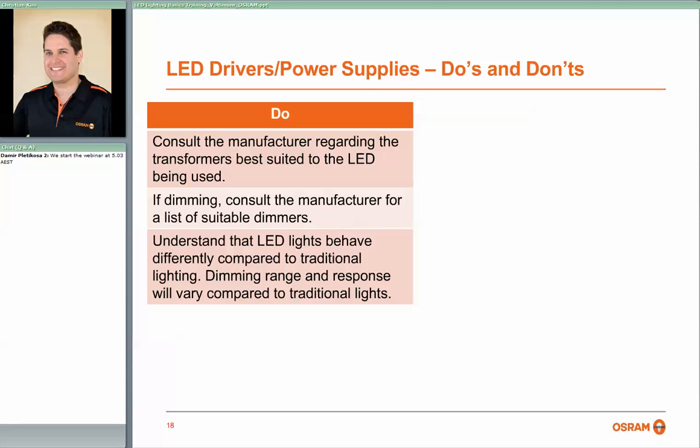products, which are designed to work on existing technologies such as halogen transformers and so forth, where you're just replacing a halogen lamp and putting an LED retrofit type lamp on there. You have to make sure that the actual transformer is capable of operating the lamp without any issues. Some transformers can have issues with minimum loads. For example, a lot of them are rated at 20 watts as a minimum load, so you can encounter issues where you underload your transformer, and then of course that results in no light, or sometimes you can get flickering.